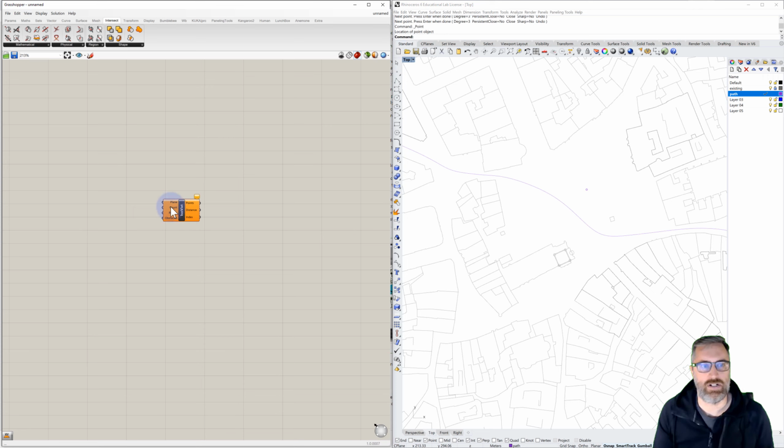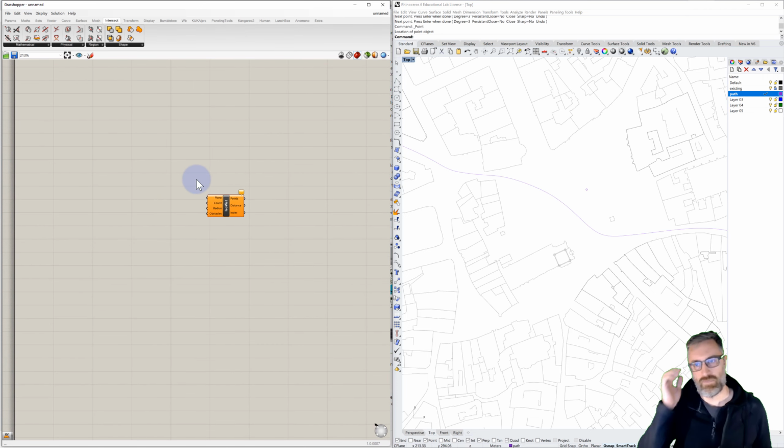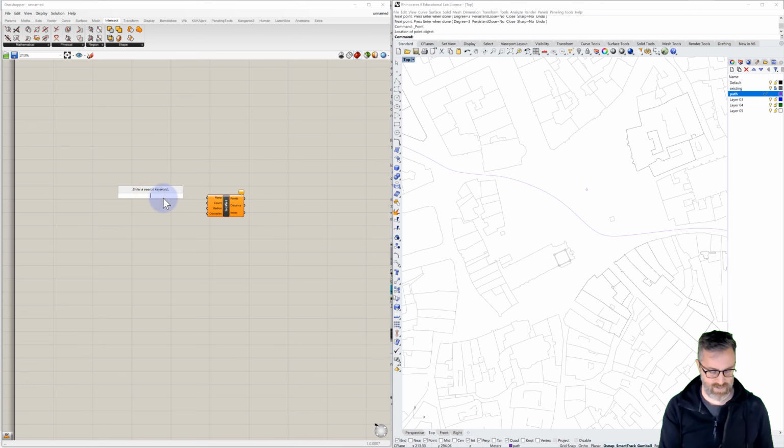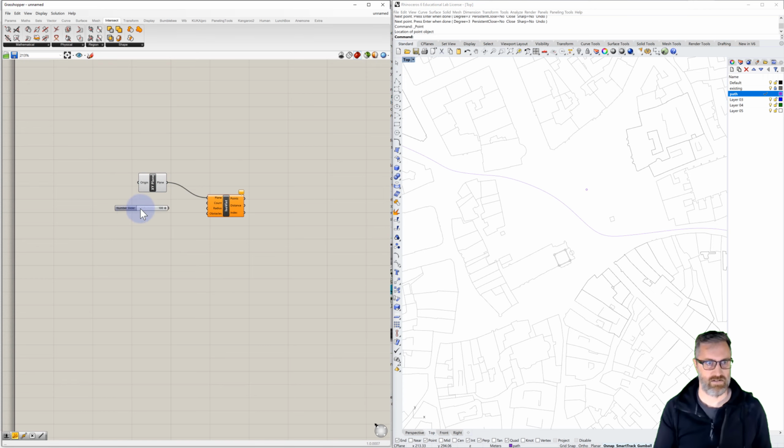And so there's a couple of things that we have. I also want to introduce a new tool as it relates to this. So let's start with the plane. We've defined planes in a number of ways. Let's use XY. It's our XY plane. And we'll set that for the plane. And we're going to make two sliders. We'll start with 100 for each of them, and we'll go from there. We'll see if they work. We'll set the count to 100 and the radius to 100.